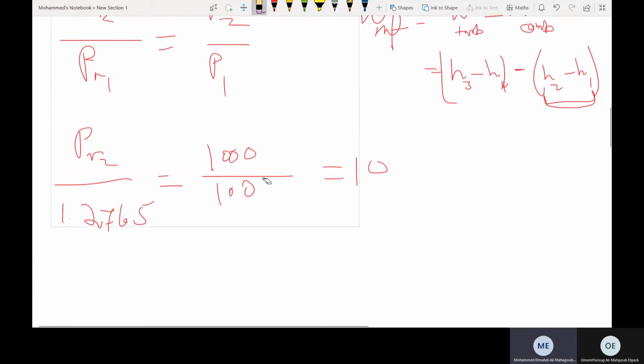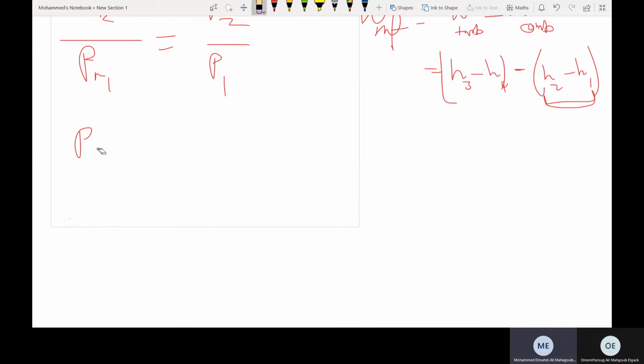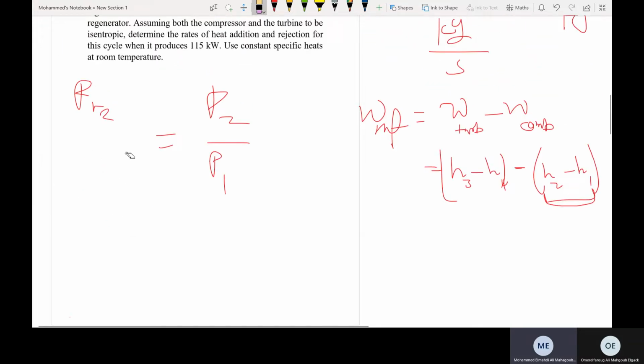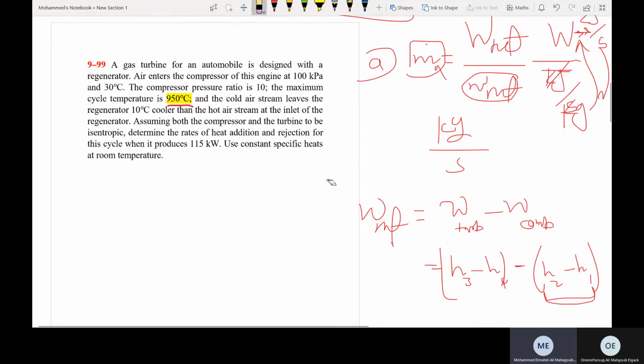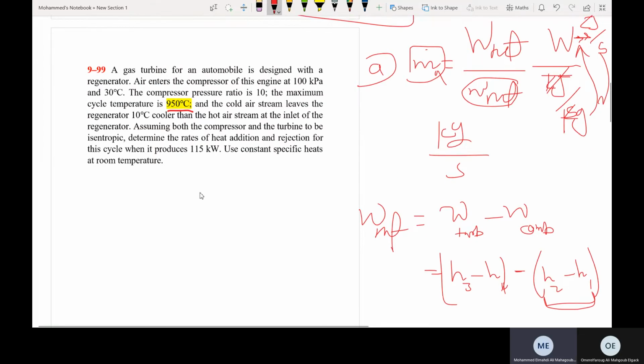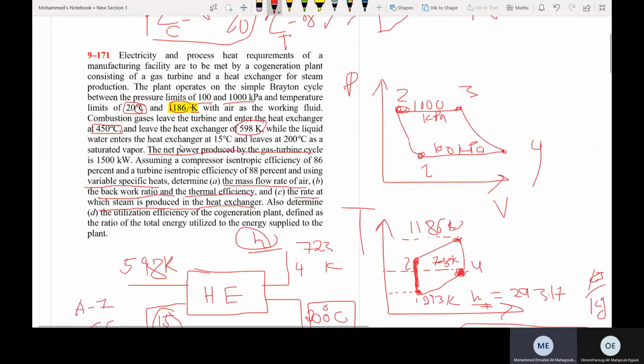And remember, you have two processes that are isentropic or can be isentropic with some deviation. Those are the points where you can use the relative pressure ratios in this standard assumption. And you have two processes where the heat addition takes place, so you cannot use the pressure ratio relationships in these two processes.